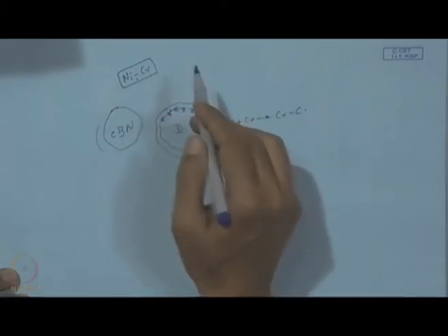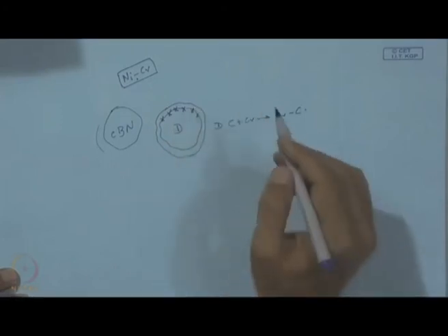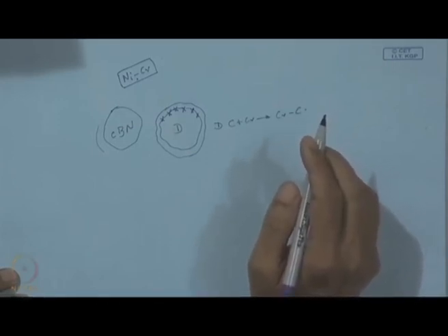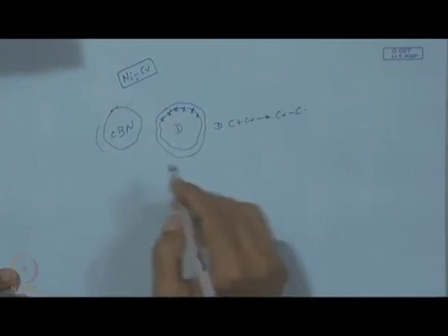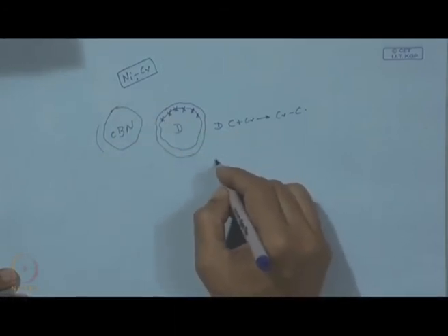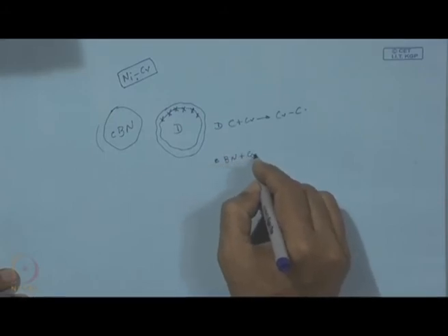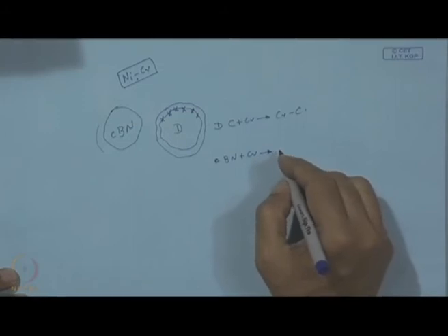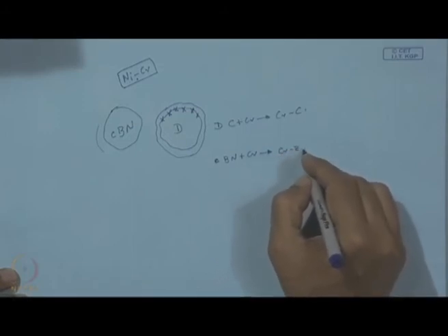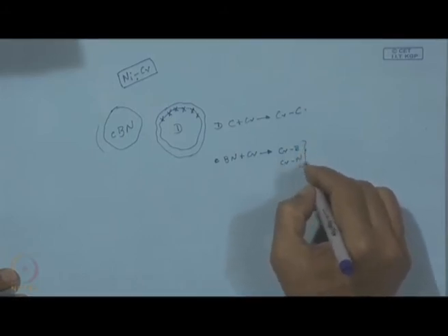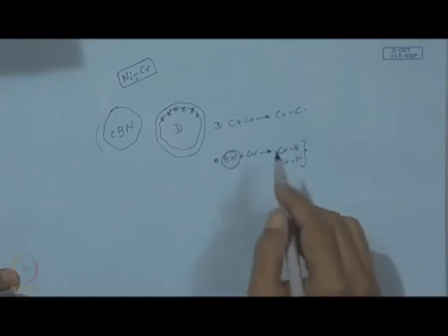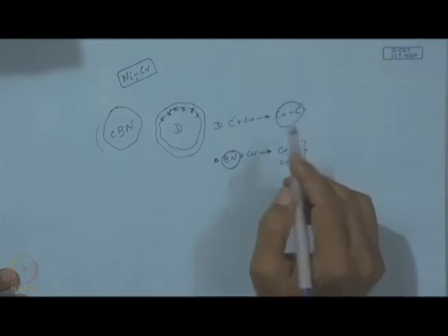When this material becomes a liquid, then chromium segregates towards the surface and we can have very good bonding and wetting. But this is just not possible with CBN. When we have this chromium with CBN, that means boron and nitrogen and chromium, which is actually a strategic material, the thermodynamic properties do not suggest that chromium boride or chromium nitride are evident and will form. That means CBN is more stable than these two, whereas chromium carbide is more stable than carbon or diamond.